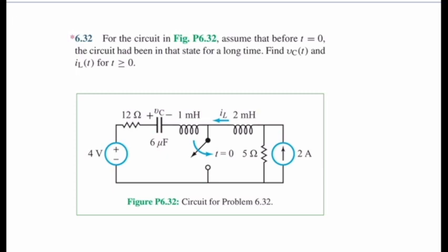That wire at the top and the bottom, you could physically redraw them. When you have a common wire like that, you could actually draw them as separate circuits. So in the beginning, before the switch, they do connect, because you have current just flowing all through the 2 millihenry, 1 millihenry, and resistor. So that becomes a whole branch.